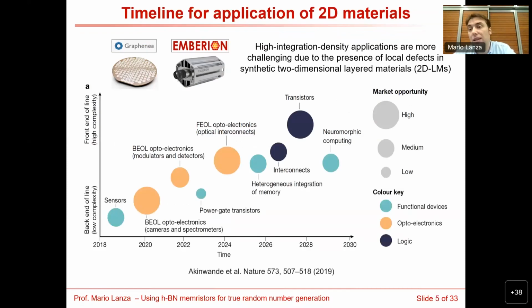So if you take a look at the semiconductor industry, you can see that new materials have always been studied. The first transistors were made of germanium, then silicon was employed for economic reasons. The material for the contacts has also changed from gold to interconnections made of copper, aluminum, and contacts made of titanium nitride. And for the insulators also, silicon oxide was the preferred insulator for silicon transistors, but now the transistors are using hafnium dioxide.